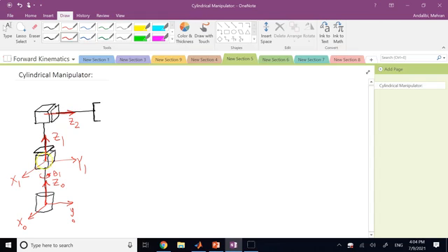You clearly see that's where I select point O1 to be. This is point O0. Then I go to the next one. This time my Z1 and Z2 are already intersecting at this point, correct? If you continue Z1, you see it is intersecting Z2 at that point. And so according to what we learned in the previous slides, this is going to be my origin for frame 2 already. So that is set. Good. So that is O2. I got it.